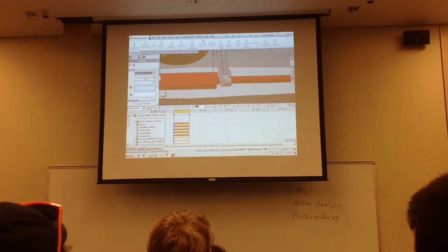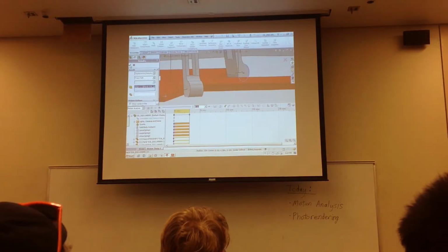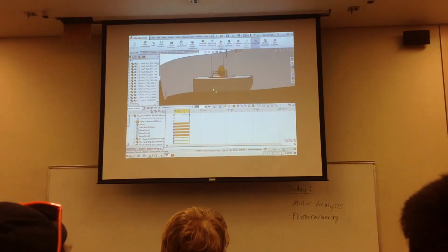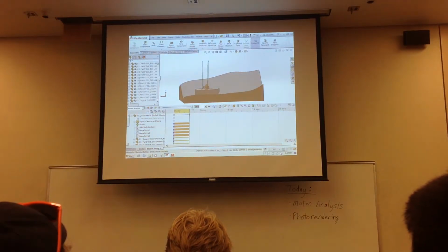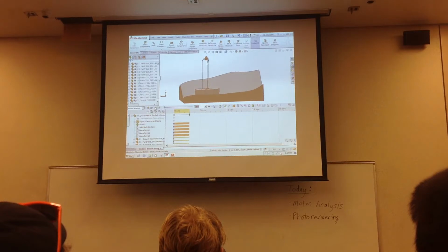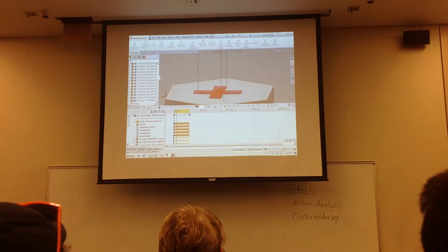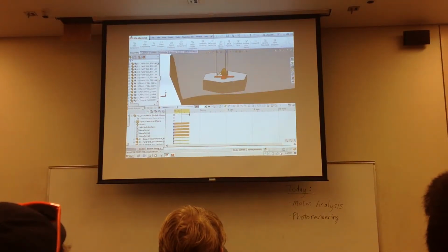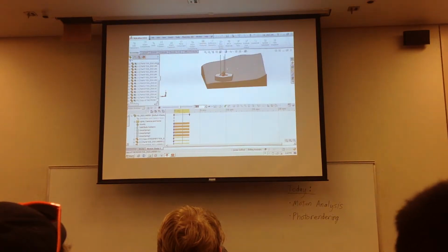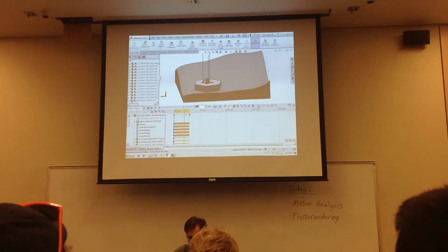And one more time, displacement, trace path, choose the other leg, say OK. Okay, so now this allows us to see, if we rewind that and replay it, we can see the precise path the egg took, or the feet took, once they hit the ground. In this case, it didn't bounce around too much, but if we had the one where it bounced all the way off the landing pad, that would be a little bit more entertaining to see. Okay, so that's one result that we're interested in.